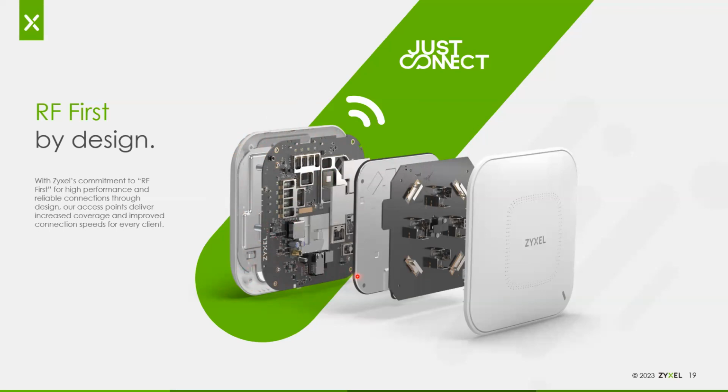The next thing we do here has to do with RF performance. So you'll notice here we've got a lot more shielding on our main board than you would normally see on our competitors' access points. And the reason for that is, in addition to the normal EMI and Wi-Fi shielding that you need on your board, we also provide additional filtering to block out 4G and 5G signals. So 4G and 5G can operate on channels that are right next to 2.4 or 5 and can bleed over.